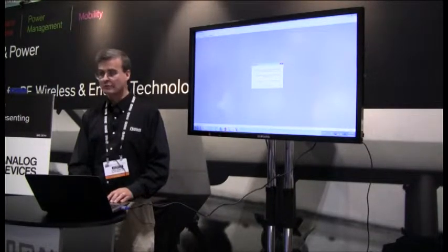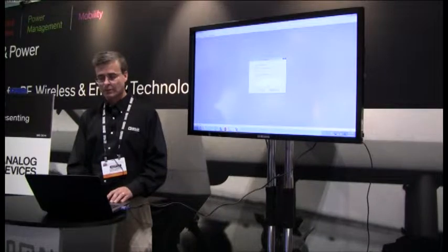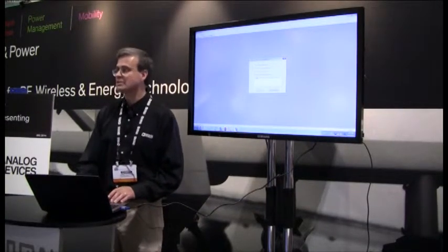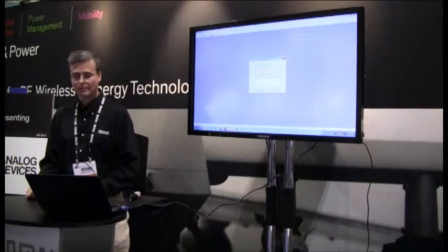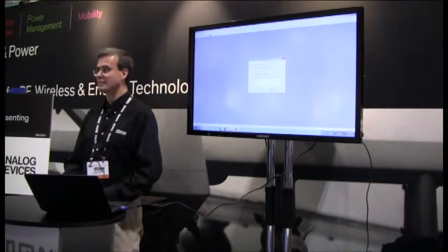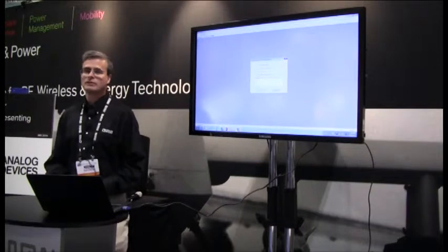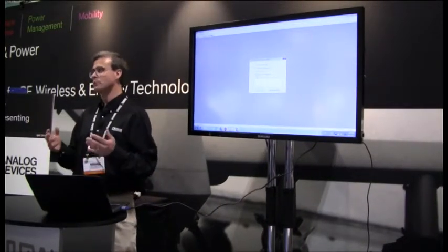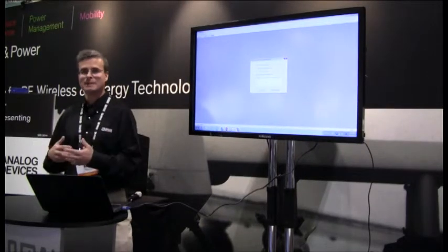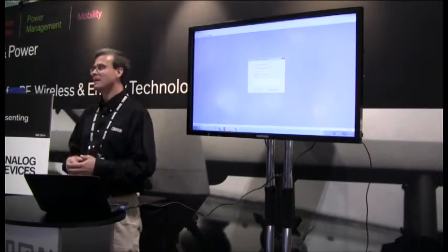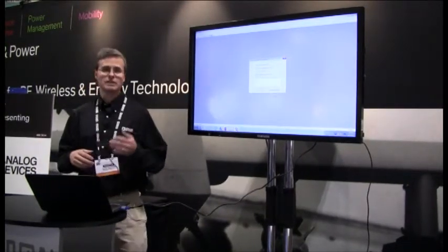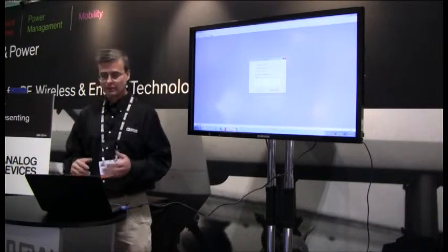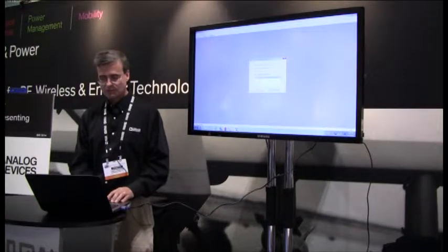And again, you have a tutorial that you can choose from, but I'm going to go straight in and start with an application note. So this is a setup of one of our PLLs. It's the ADF4158. The ADF4158 actually has a signal generation capability, so you can do ramping waveforms. It's meant for sweeping. It's a PLL meant for sweeping, and you can do different waveforms like triangular waveforms or FMCW even if you would choose.